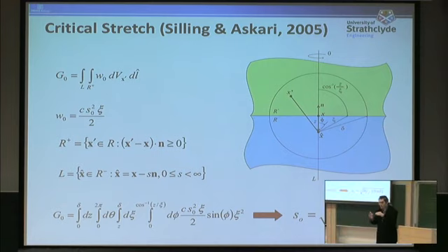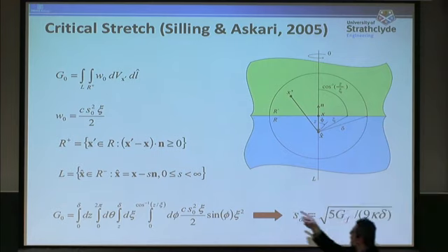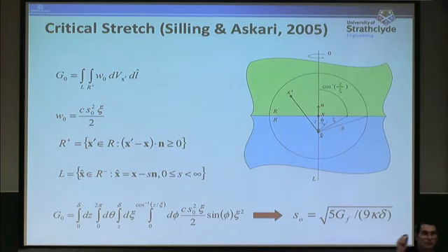Before breakage, the energy of each bond will be that omega 0. So this is the energy of each bond just before the breakage. You need to break all the bonds passing through that crack surface, and when you sum them up, that value should be equal to the critical energy release rate. So once you put these two together, you obtain this particular relationship.